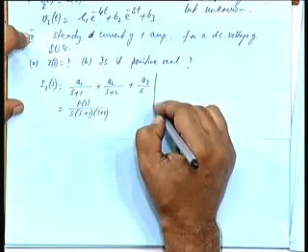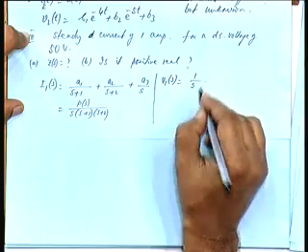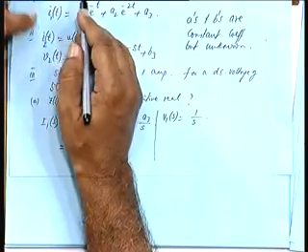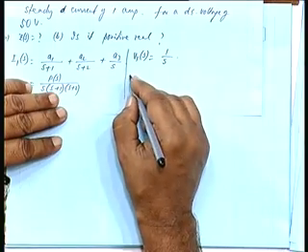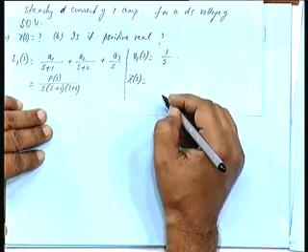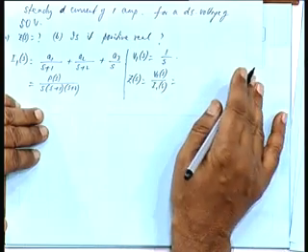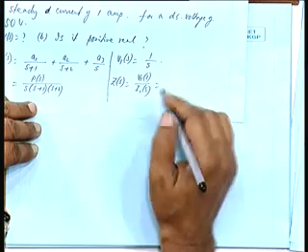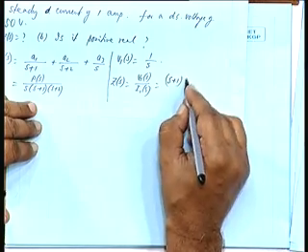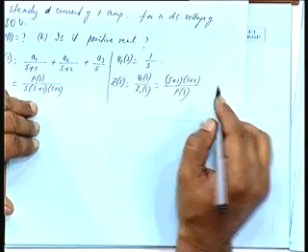Okay. What is the corresponding V1(S)? Input is unit step, is it not? So, 1 by S. So, what could be Z(S)? V1(S) by I1(S). So, this divided by this, how much is it? S plus 1 into S plus 2 divided by some P(S), not known as yet, but the numerator factors will be S plus 1 and S plus 2.